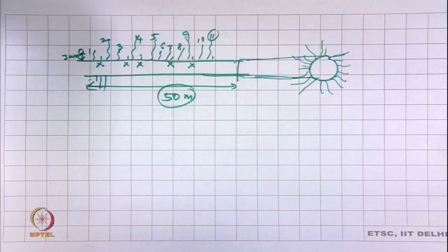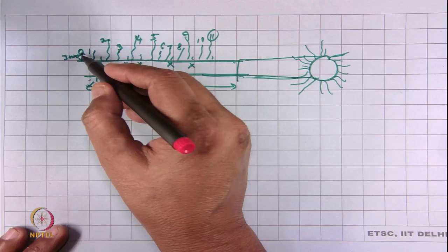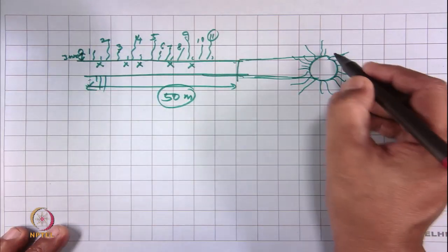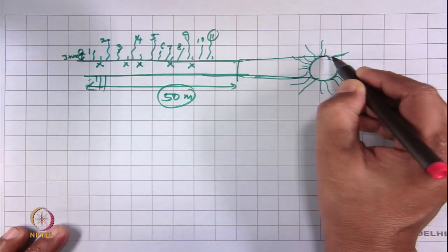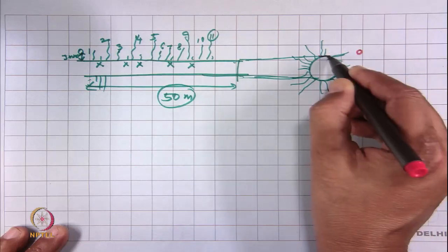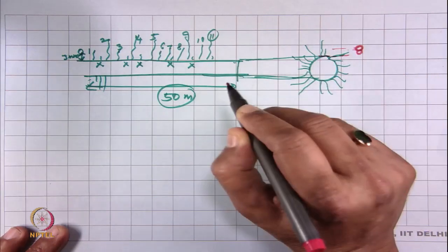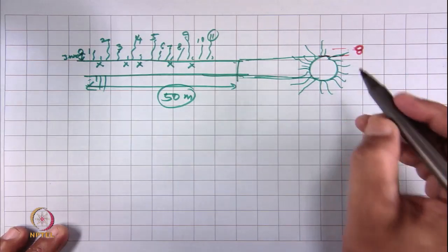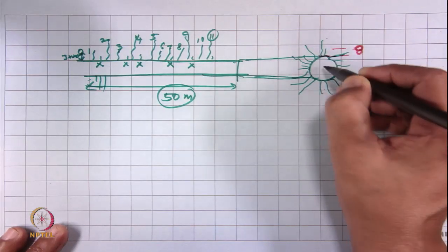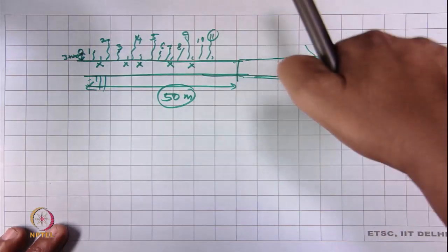Now, what is happening here? This photo sensor sends only from one point, not even a surface, only one point. Suppose this is a sensor, placed beyond 3 millimeter. The yarn is moving in this fashion; this is the yarn movement direction.